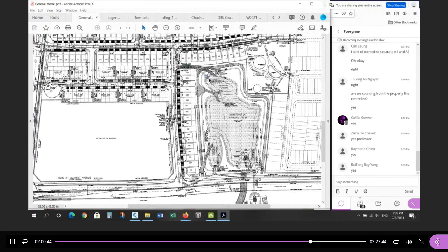So the sewers outlet here out of this head wall, and then it's treated here, and then it overflows into here, and then there's another head wall here. So there's a storm sewer external to the site that actually dumps into the pond here, and then eventually the flow makes its way out here. So this is the stormwater treatment pond. All the sewers flow to this pond.